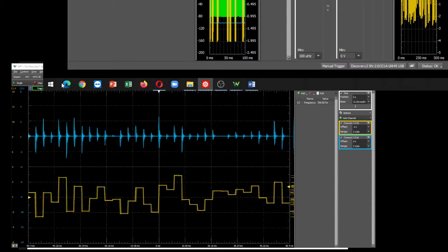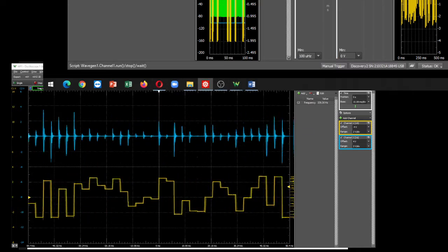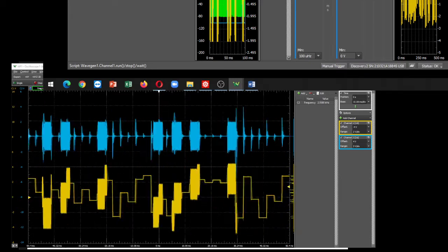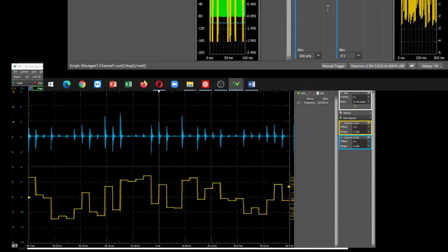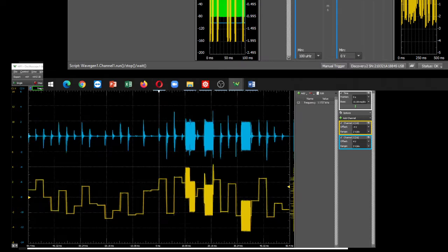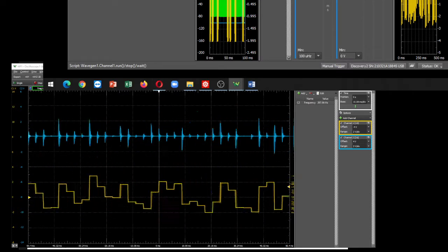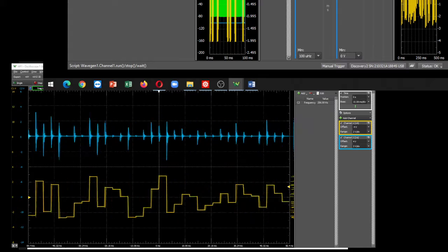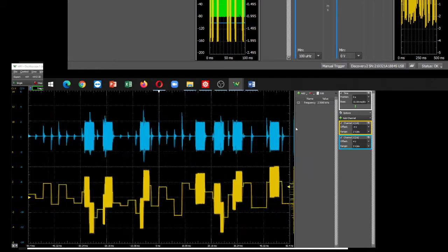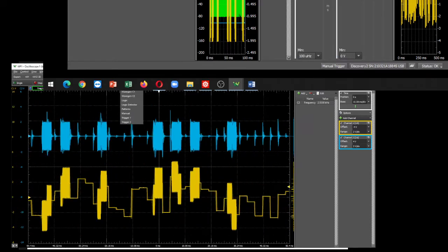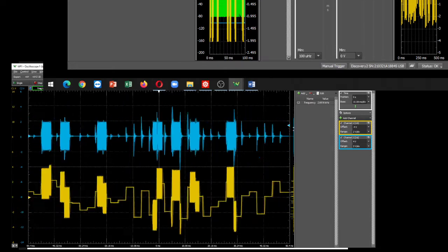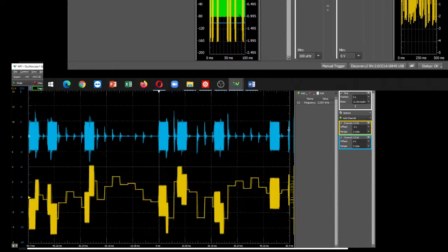Observe the signal being on and off alternately. One can see that thanks to the high frequency modulation, the original portion of the message signal is allowed to pass through, while the added noise, without high frequency oscillation, is not. In fact, the filtered signal, blue, top, is more stable than the noisy signal, and it can be used as the trigger source.